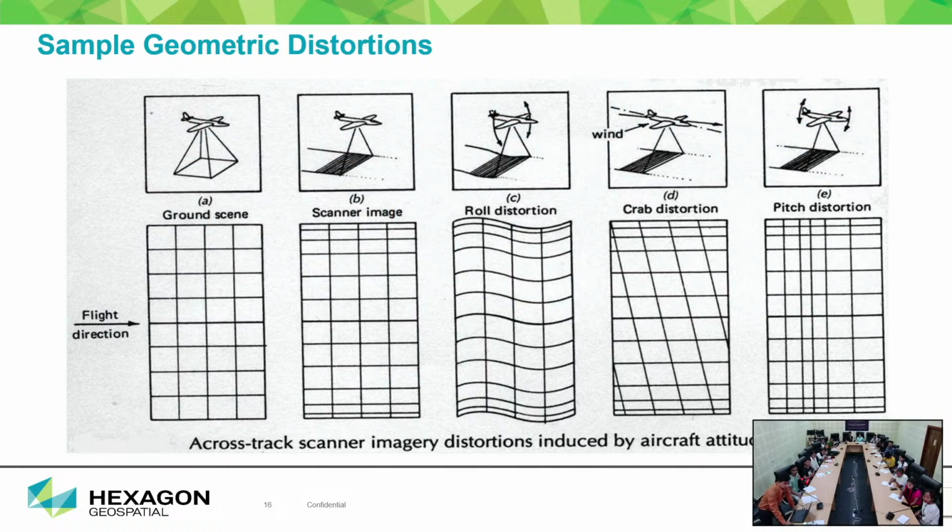You can see here an example of some distortion. This type of error may come from the ground features. Suppose you are taking a picture of some flat land, and this picture has some flat parts and some hilly regions. During data collection, you may be getting the view from the left angle, then the right angle, and in the right angle there will be some shadow. Due to the shadow, you are not able to identify the features where the shadow falls.